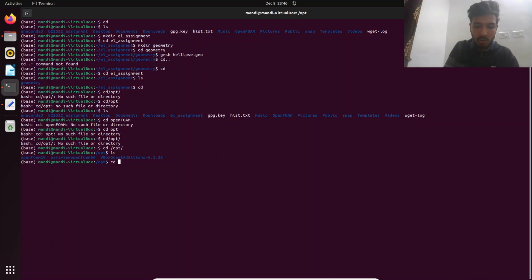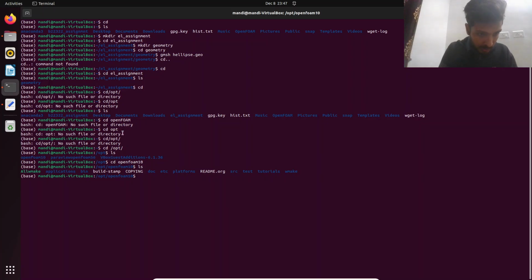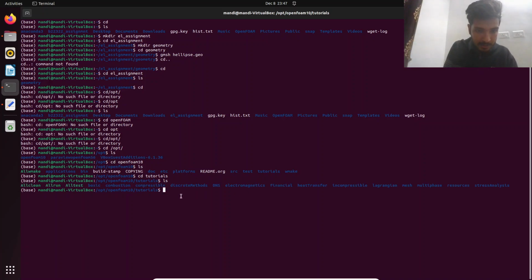So CD OpenFOAM 10. Okay. Again, checking the folders which we have over here. So we have applications, bin, build stem, and many more, but we will go with the tutorials one. So CD tutorials. Looking at what tutorials we have, take ls, listing it all out. So we have a lot of tutorials that we can solve. Like we can solve a lot of problems with OpenFOAM. It's a very versatile one.